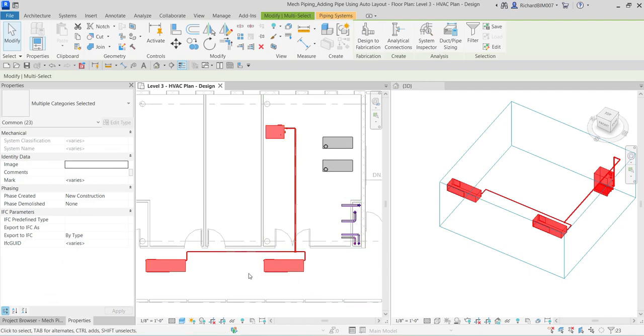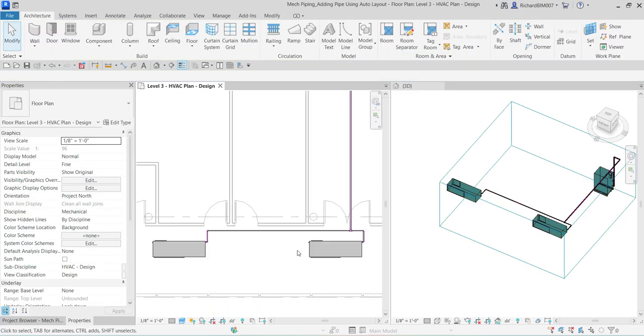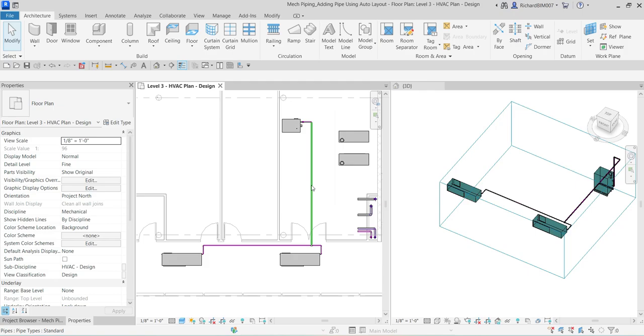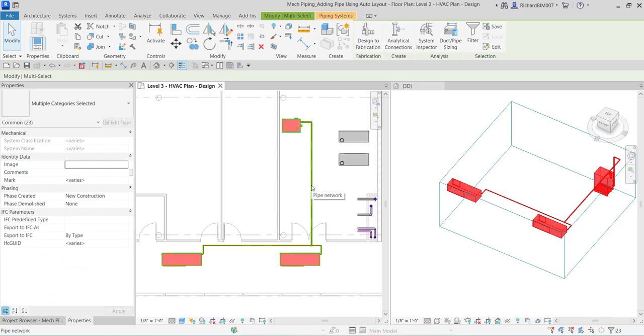Again, you can also do this tabbing in your ducting. So you hover your pointer, like for example here, and then press tab, and tab again, and tab again. As you can see, it highlights all the elements that are connected to the system. So this is one way of checking if your equipment is connected properly to the system.